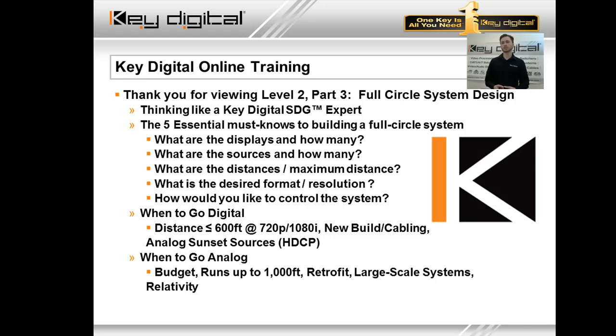Also, consider any of the sources that your customer is bent on installing into the system, any of those sources, what we call analog sunset type sources, with that copyright protection encrypted. If it is, we have no choice but sticking in the digital realm. We cannot convert that signal to analog. When do you go analog? Budgetary reasons. Runs up to 1,000 feet, so those runs that go beyond 600 feet, certainly we're not going to have much option outside of going analog or getting creative.